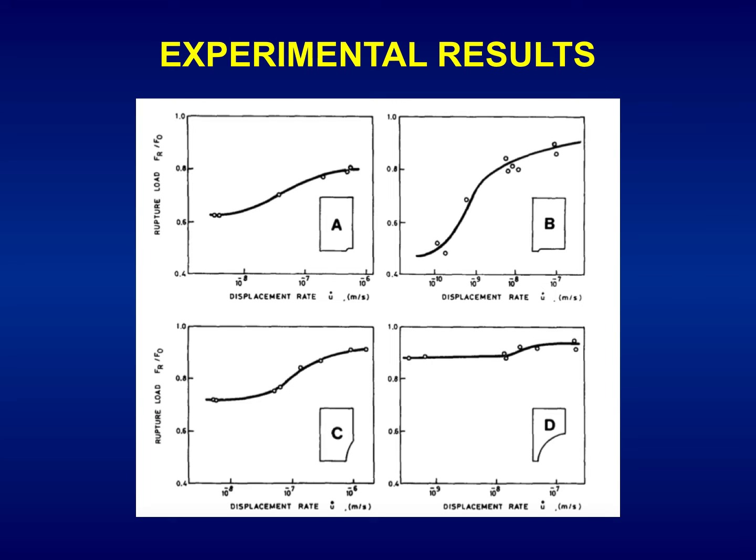There are 2 asymptotic values in all plots. Apart from this increasing trend with the displacement rate, we have the quasi-static test left-hand asymptotic value, in which for low displacement rate, the quasi-static steady state condition for hydrogen diffusion and equilibrium in the sample is achieved.